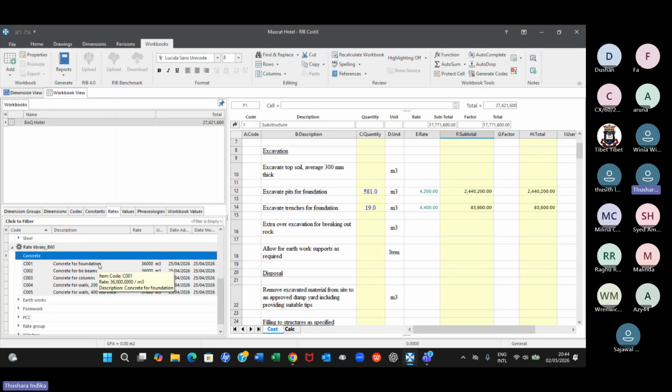And also, if you are working for a consultancy firm, when they prepare most of the time engineer's estimate or tender estimate, they don't want to go into the rate analysis like a contractor's QS does, right? What they do is they go to some market prices and then price the BOQ. So that is what we call a tender estimate or engineer's estimate, right?